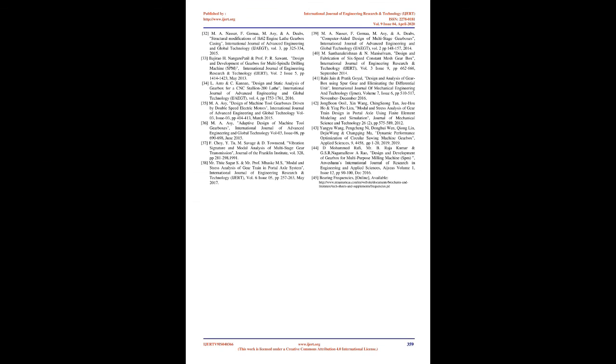The less deformation, the higher the stiffness. The maximum static deformations at the spindle head for modifications number 1 to number 4 decrease by 29%, 28.5%, 28% and 31.2% compared with the original one, 145.1 µm. This means that modification number 4 improved the milling machine structure by 31.2%. The reshaping of the milling machine column increases all natural frequencies for all modified structures. The natural frequencies of all 10 first modes of all modifications are higher than those of the original structure.